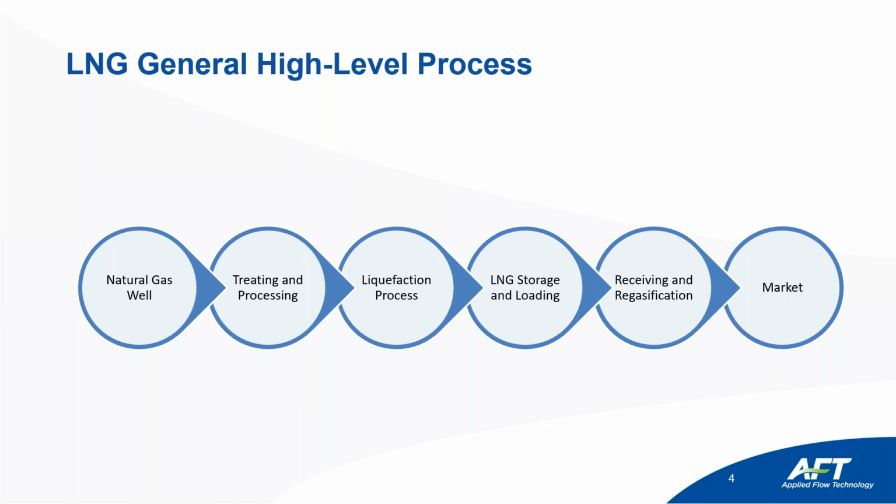After the liquid LNG is transported to wherever it is desired, it will be shipped to receiving and regasification, where it will be boiled back into a gas so that it will be usable as a fuel. From there, it will use typically pipelines and things of that nature to be shipped to the market, where it will be used for power plants, it will be used for chemical processes that need methane, and it will be shipped to people's homes for heating and cooking, things of those natures.